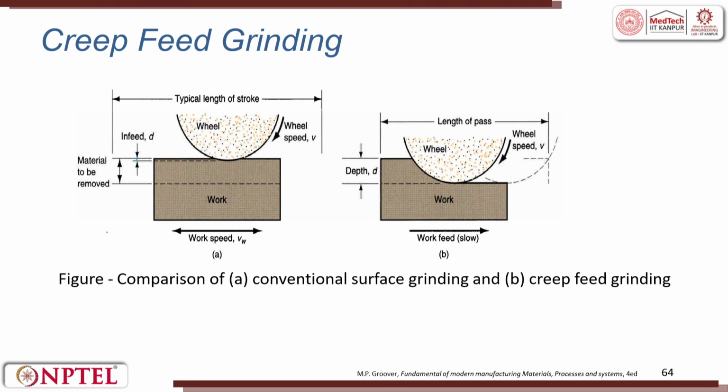So, the infeed is this much. So, the material to be removed is this. Here, this is the conventional way of doing it. In creep feed grinding, we do the depth in one shot. So, naturally the grinding wheel should be harder, the abrasive should be better, all these comparisons are there.